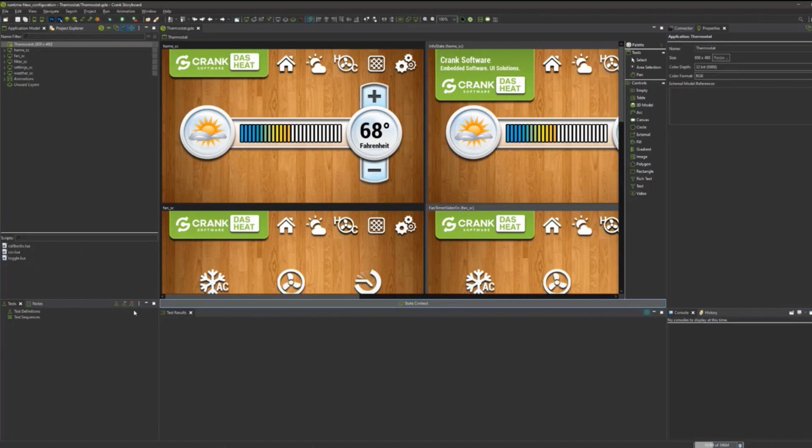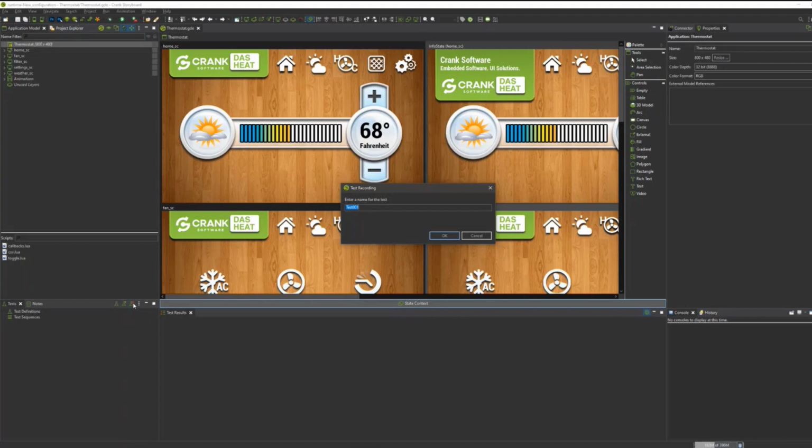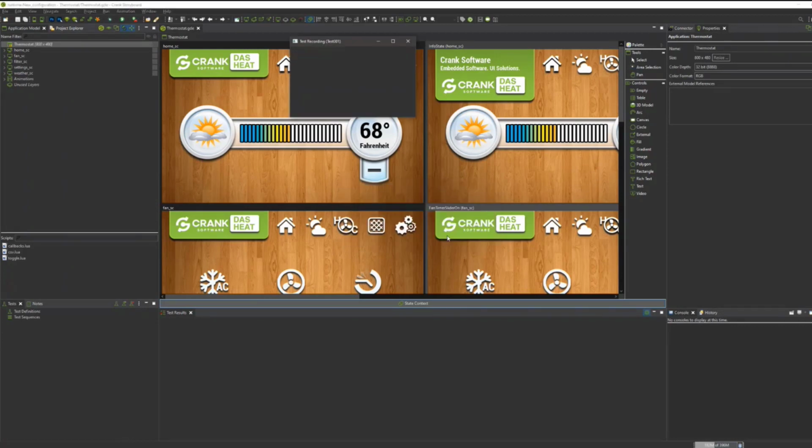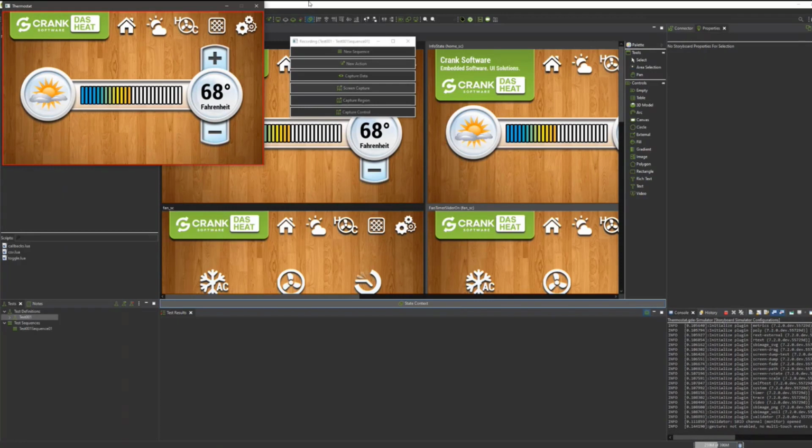One of the main ways that tests are going to be created is through the test recording action here. So we can trigger a new test recording. I'll give it a default name, test 001. That's fine for now, for demonstration purposes. Once the recording starts, this starts a capture playback, which records user input that will be played back in the test.